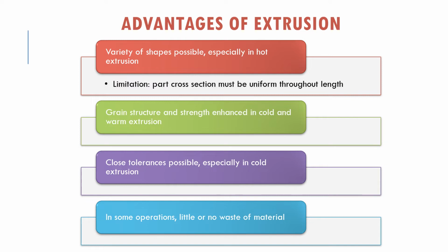But the limitation will be part cross section must be uniform throughout the line. You cannot change the shape of the workpiece in between of the operation. Okay, so the grain structure and strength will be enhanced in cold and warm extrusion.